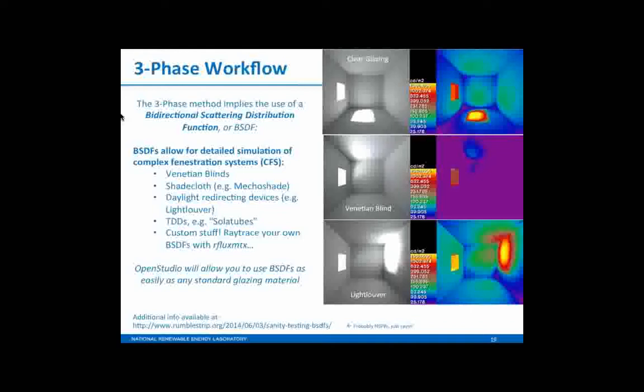So this is why it's important, because if you just look at a whole building energy model and you throw a bunch of weather at it and you say, well, the daylighting is great, there's daylight in there all the time. But the reality is the user's probably going to take some kind of action for half the year, while the actual daylight performance is going to be wholly different than if we just did it this way. So this is where these BSDFs come into play.